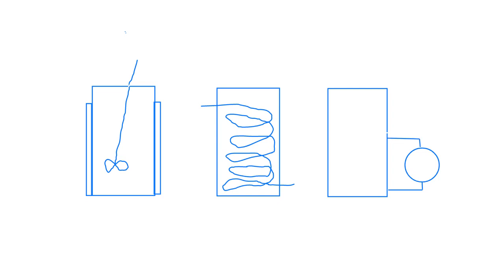Like that. So you can just remove the heat, you cool down, the liquid goes back into this CSTR essentially, and you can make that heat exchanger as big as you like, and you can have the recycle as fast as you like, and you will still manage to keep that reactor cool enough. So those are the three options I talked about.